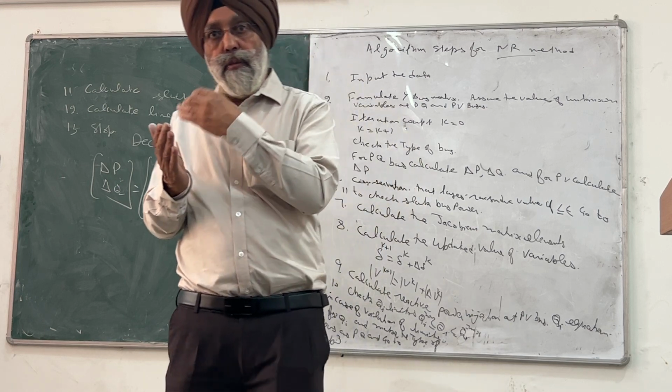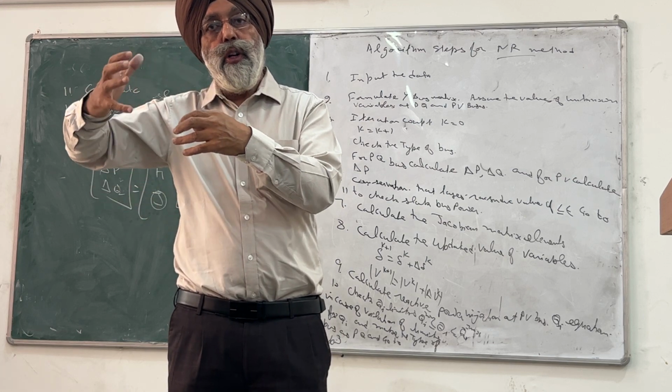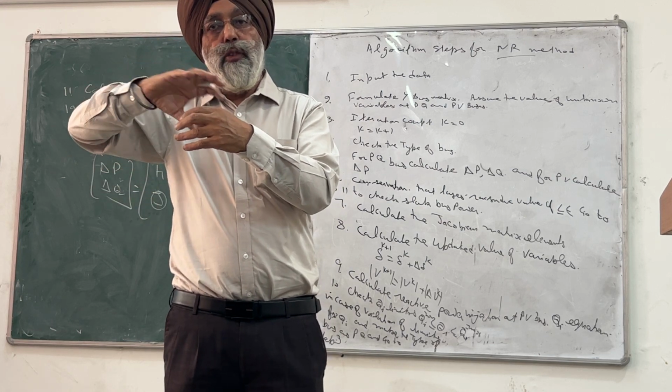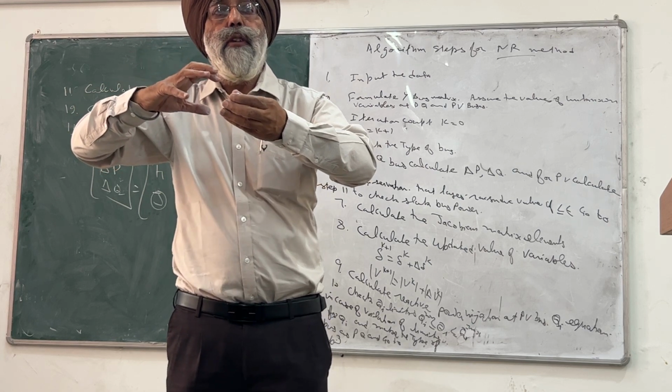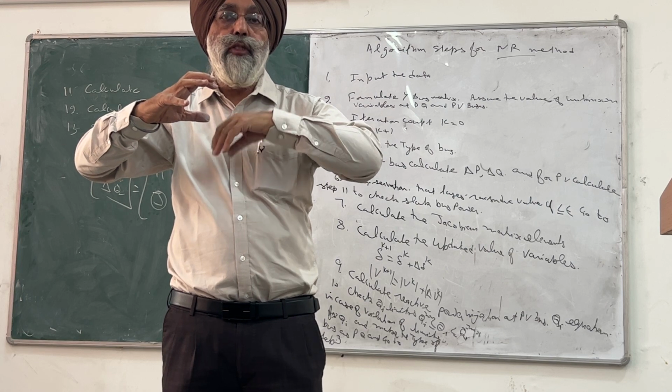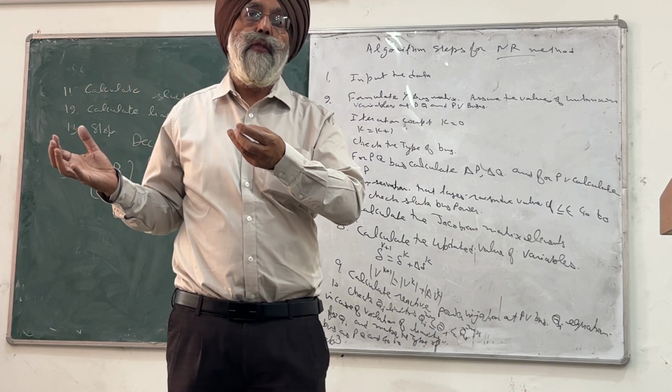So when you put more and more load, it tries to slow down your rotor. So we need more mechanical power on the mechanical side, as we are now getting more electrical power.